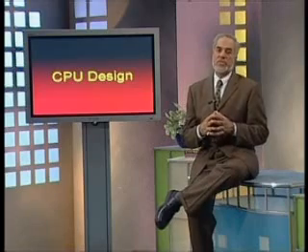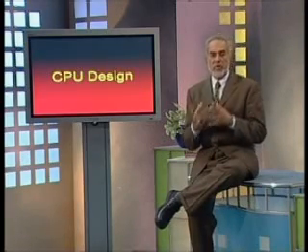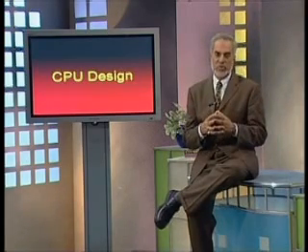Now, you remember immediate mode, for example, takes the operands right from the same instruction. It may be available in the form of a data or an address, or correspondingly the immediate mode usually defines the operand as a part of the instruction. We also discussed the register relative addressing modes and the memory relative addressing modes, the base or indexed addressing modes.